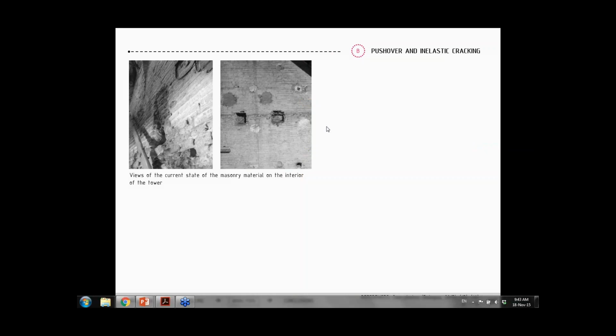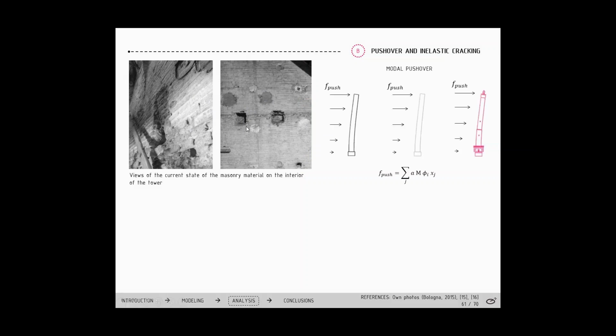Okay. As we know, sometimes the linear analysis cannot be representative of the structure's real behavior, and therefore it is necessary to perform a nonlinear analysis to obtain the ultimate limit state response. The European codes consider the implementation of nonlinear analysis for structures in which the residual strength and stiffness are influenced by the present damage, in this case the historical constructions.